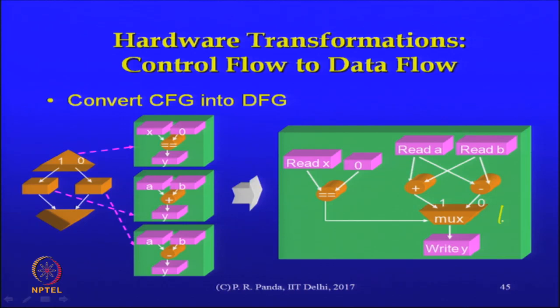Yes. This is only a DFG as of now. You could schedule the DFG in the following way. That could be scheduled in one. This, for example, could be scheduled in a different cycle if we wanted to. Remember, the hardware from this is not obvious yet. It is possible that we can share both of these on the same function unit like an ALU if we wanted to. Yeah, that kind of a hardware is of course meaningful. It does mean a little bit of an extension of our abstraction. Now, I should have a multi-function unit that is capable of doing both the plus and the minus.